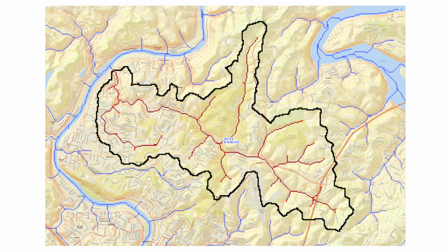What we want is this branch before it gets into the Monongahela River. If I say it slowly, I'll say it right. Monongahela. So we don't want to put your outlet in the river itself. If you put your outlet in the river itself, suddenly you've got tens of thousands of square miles. But if you have it several pixels upstream from the river, then that's going to tell us the area of the watershed that dumps into the Monongahela at that location.